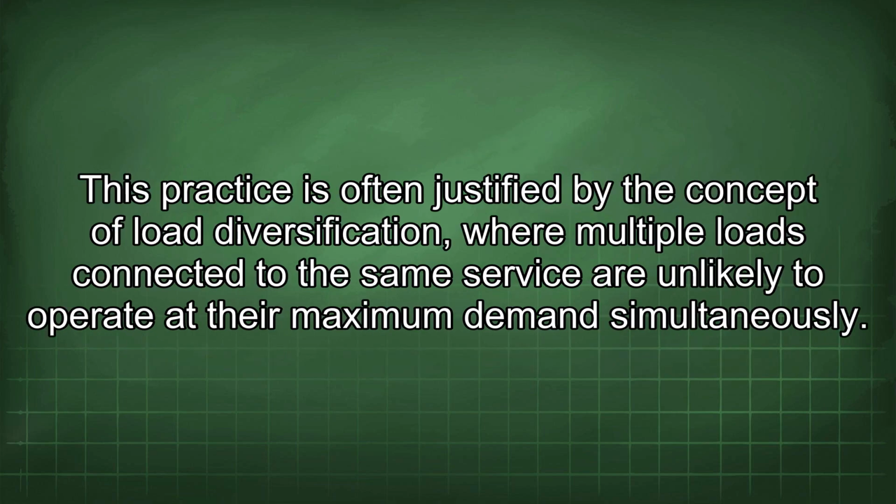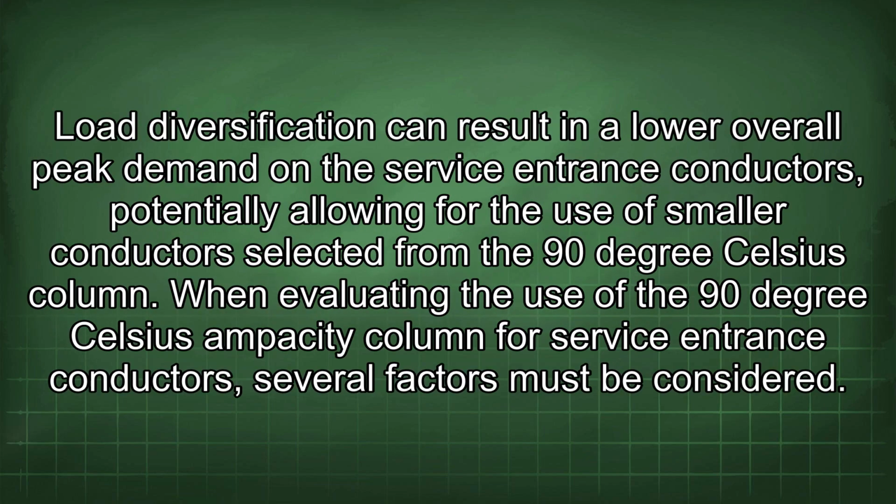This practice is often justified by the concept of load diversification, where multiple loads connected to the same service are unlikely to operate at their maximum demand simultaneously. Load diversification can result in a lower overall peak demand on the service entrance conductors, potentially allowing for the use of smaller conductors selected from the 90°C column.